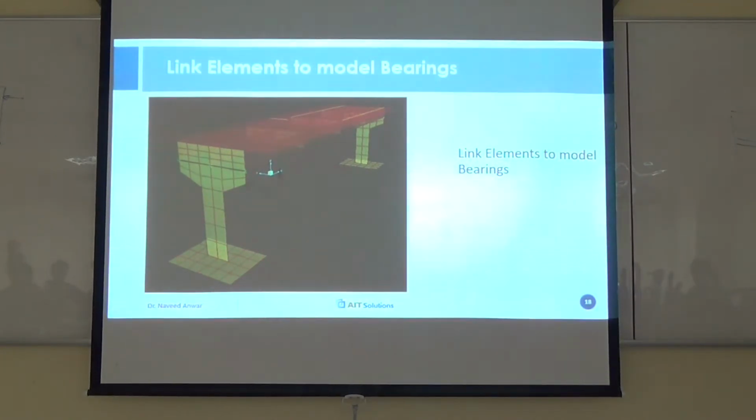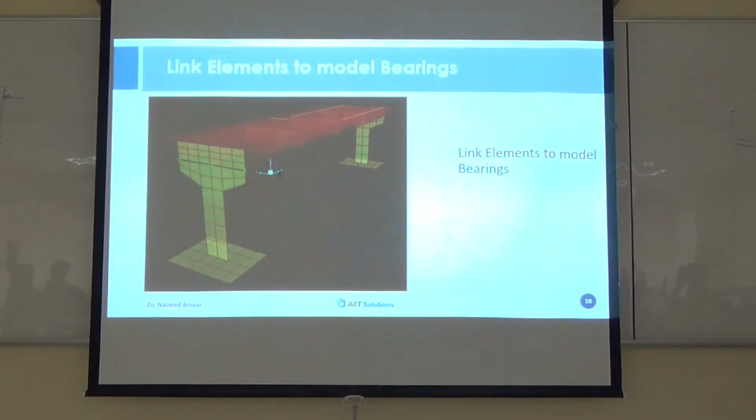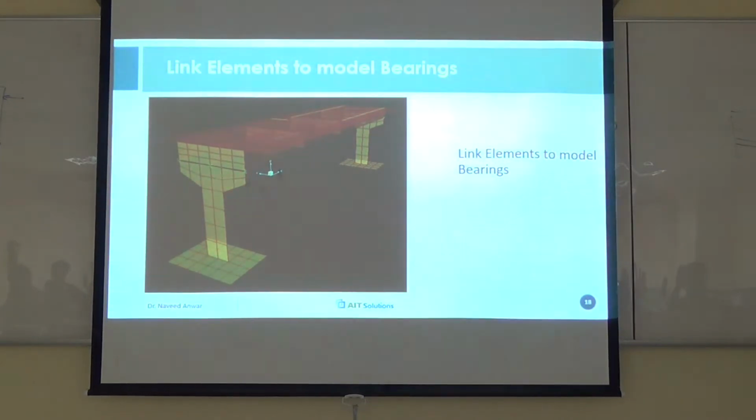It makes no sense. Same as the case, if there's a pin at the site, or there's soft connection, or a release, or a spring, you must model it. So remember always, model what is there or build what you model, but do not have them different. Otherwise, it's no point. You're just fooling yourself by making model simplification that do not exist. So we always try to model realistically whatever you have. At least make sure that everything is included. Even if it is rough, it should be there.